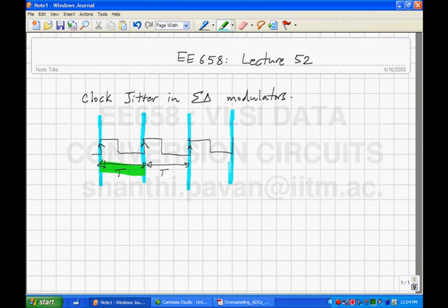So if I chop up these rising edges and superpose them all on the same graph, then if the clock was ideal, I should get only something like this, because when I cut and paste the cycles on top of each other, the edges will all coincide. In practice, there is jitter. In other words, these edges do not all line up. So there is random jitter.